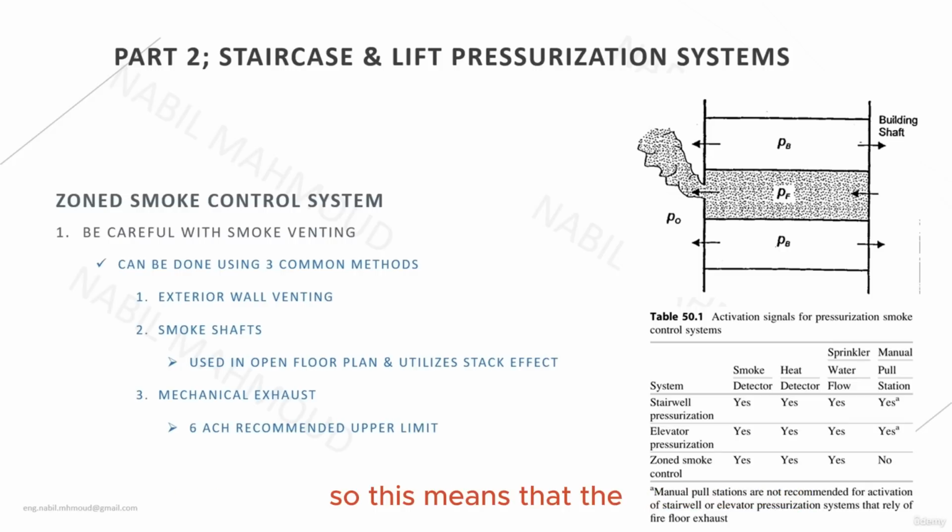So the wall you put the vent on has to be an exterior wall. It cannot be an internal wall inside the building. But this option means that the smoke will directly exit the building, so if there is any opening like a balcony on the floors above this floor, there is a potential threat that smoke will come right up into these balconies.